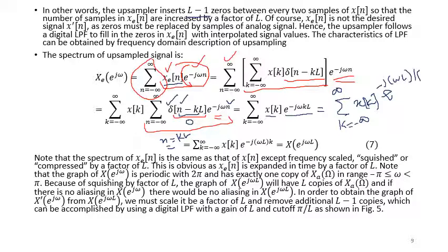If you compare with the standard equation to find the Fourier transform, we say summation n running from minus infinity up to infinity, x of n, and e to the power minus j omega n. We can also sum it if I change the variable of summation. If I replace n with k, then here comes k, and here comes again k.